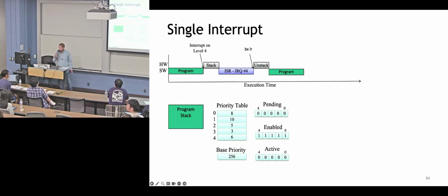When you do the stacking, why is it that it says R0 to R3, but not the rest of them? Are R0 to R3 the least important? So this is kind of like the caller-save stuff. We're going to assume that the interrupt is going to follow the ABI conventions, and it's going to use R0 through R3 as scratch space. When you write your interrupt routines, you'd have to use only those, and you'd have to save R4 through whatever. R12 is supposed to be for interprocedural calls. This would be a time when you'd want to do that. Usually the compiler does that, not necessarily you guys.